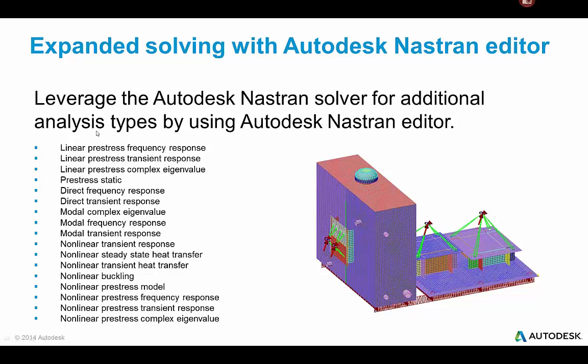So this is the entire list of analysis types that we are not fully supporting through SimMech to run with Nastran solvers today. But these are things we are working on for our future releases to enable additional solver capabilities. Of course, if you just simply export your model to the editor, you can convert your input file to one of these different analysis types, if you know the format of a Nastran input deck, and then run those analyses.